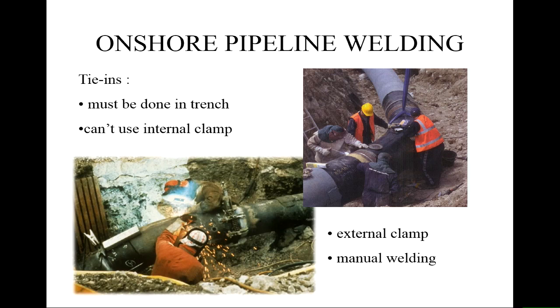But if that box had been lying there while you lined everything up, then that probably wouldn't be so good. You'd have more trouble with hydrogen embrittlement. And if that falls on the floor and you weld a stick coated in mud, then that can cause problems. So you need to be a bit careful. Welders generally are quite careful, but they do cut corners if you let them.